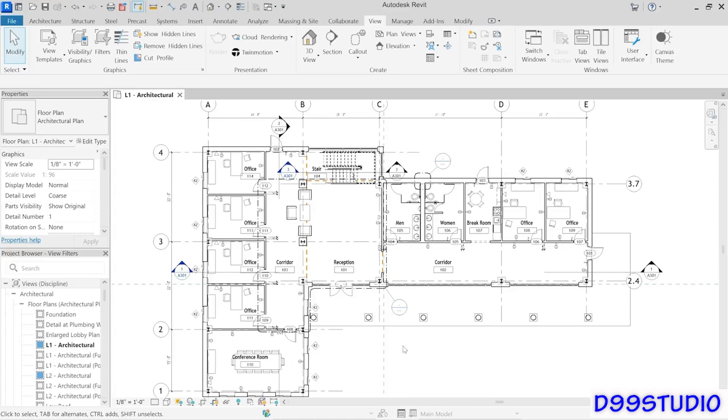So that's a much more effective and powerful way to control the visibility of those elements, because you're able to create a subset of elements based on logical criteria and then only apply your modifications to that subset. Now, I should point out that everything I've just done is just in the architectural floor plan.